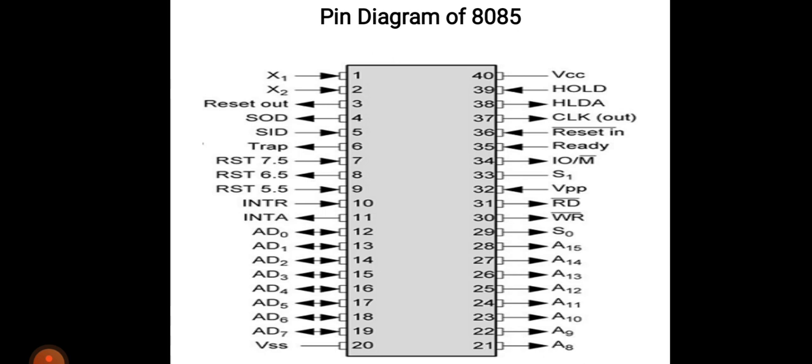This signal indicates that the data on the data bus is to be written into the selected memory or input output location. Then ALE is a positive going pulse generated when a new operation is started by the microprocessor. When the pulse goes high, it indicates address, and when the pulse goes low, it indicates data. Also, the 3 status signals are IO/M, S0 and S1.